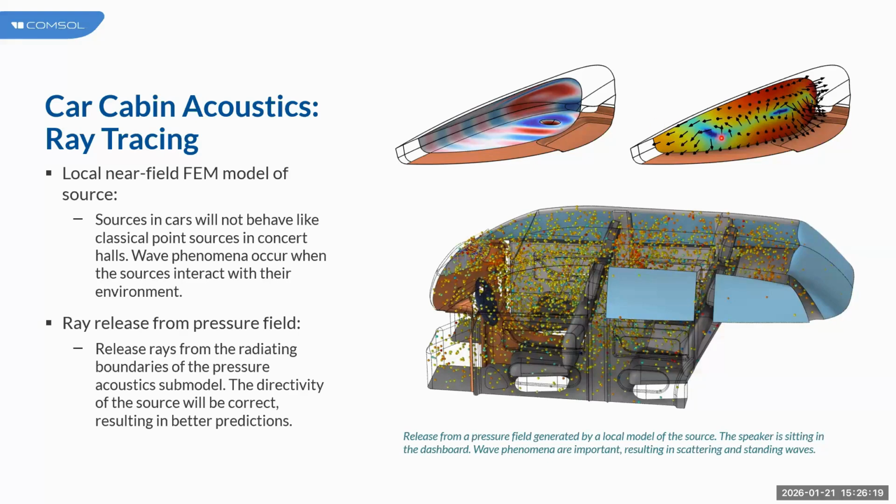So here you see the surface. And on this surface, we use the release from pressure field feature to release the near field, basically the waves, as rays to further propagate through a very large system. So the complete model here is simulated using a single model, using a single graphical user interface.